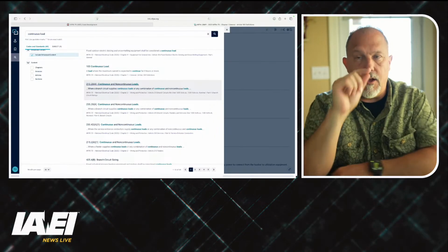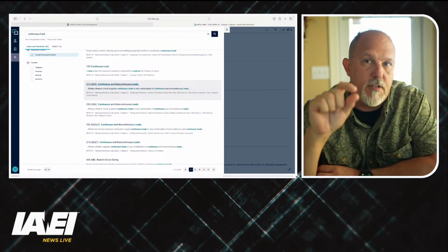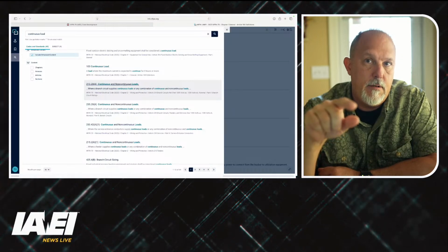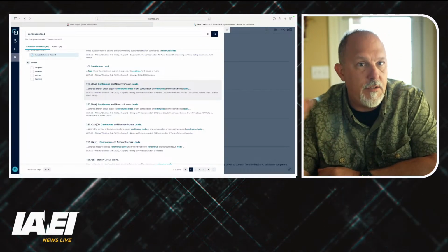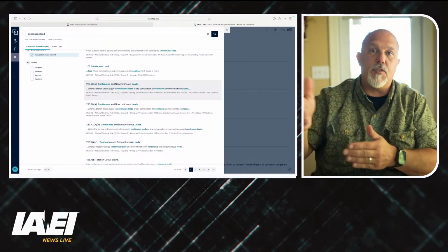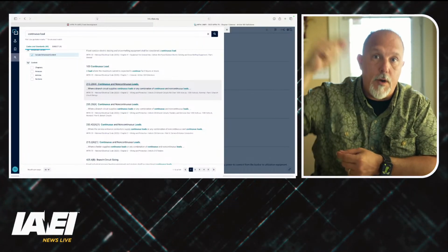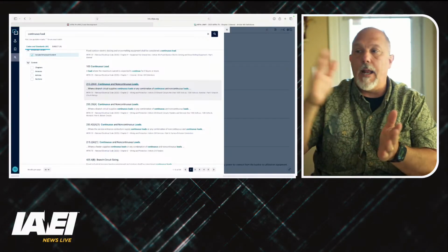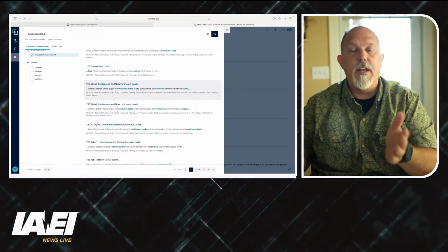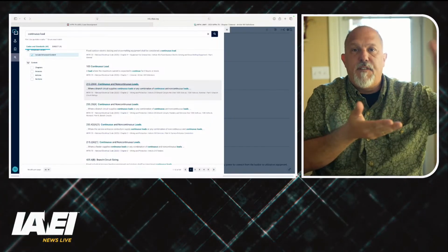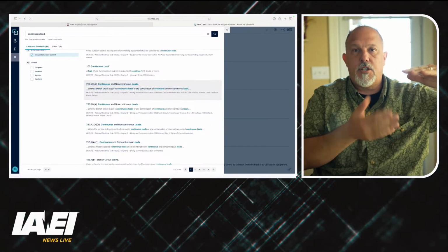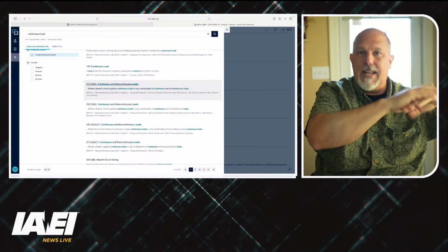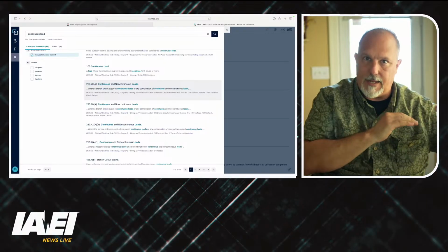In 210, it'll also tell you that the overcurrent device cannot be less than 125% of the continuous. And that's, again, 125% is 1 over 80%. 1 over 0.8 equals 1.25. So when I multiply a load current by 1.25, I am inflating the load current so that when I pick my overcurrent device, that current is going to be 80% of the rating.